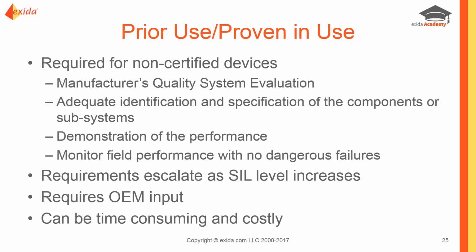And not all devices are going to be SIL certified. There's a lot that need to go through the proven in use process. So when you're trying to develop a proven in use process, if you've got some history and operating experience, you can go back to the old history there and try and develop it, but you're also going to have to get some input from the original equipment manufacturer, and this can be a time-consuming and costly approach.